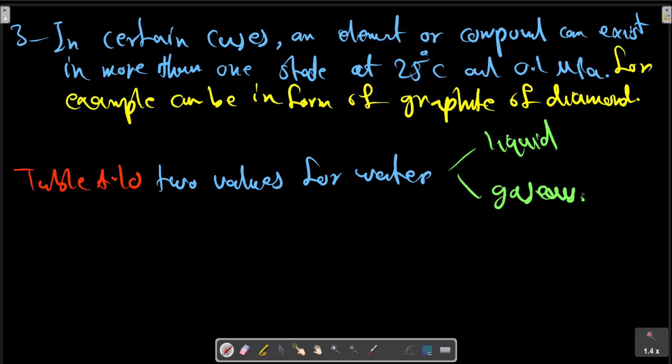Frequently, students are bothered by the minus sign when the enthalpy of formation is negative. For example, the enthalpy of formation of carbon dioxide is negative. This is quite evident because the heat transfer is negative during the steady flow chemical reaction, and the enthalpy of carbon dioxide must be less than the sum of enthalpy of carbon and oxygen initially, both of which are assigned the value of 0.